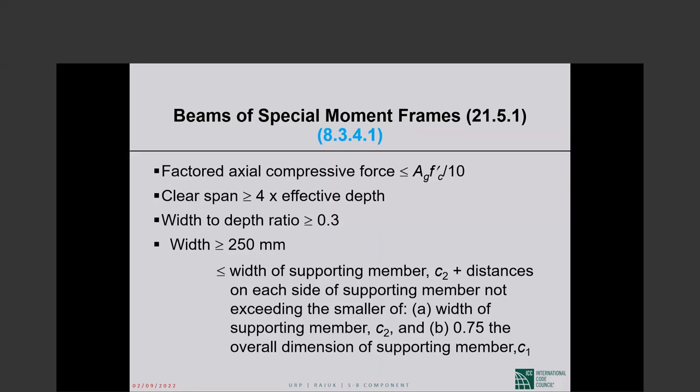So 21.13.6 was already available, and it looked like a very attractive alternative to living with a limit that was very, very stringent. But I emphasize, I never said that flat plate column frames cannot be used in design category D. They cannot be used as part of the seismic force resisting system. There is a huge difference between the two statements.